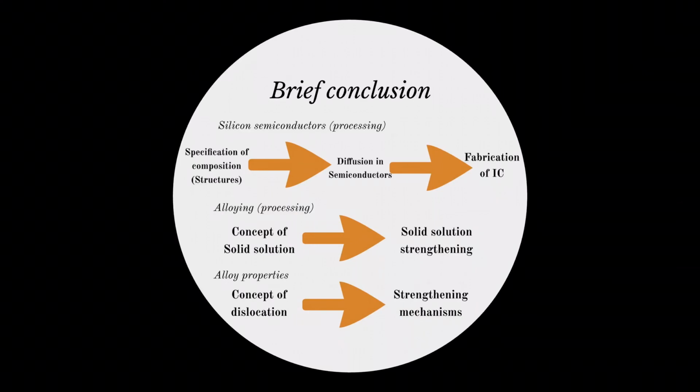So why is it happening? That's because when you are deforming the metals, the dislocation moves, and that's when the materials deform plastically. So that's why the metals didn't break at that point. It should be broken, but it is strengthened because of the dislocation.